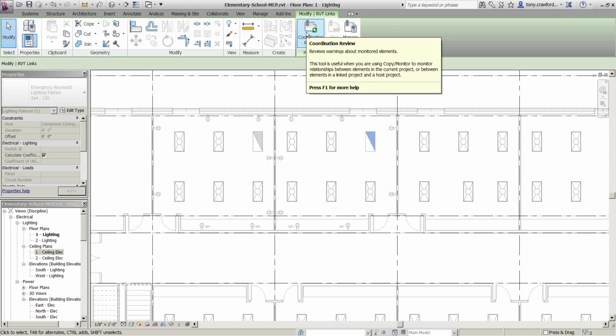And basically what that's telling Revit is keep monitoring these two, monitor mine versus the original, and if anything changes, make this the new normal. So now that they're really on top of each other, keep monitoring it, but use this as your reference point now instead of the original point where the insertions were the same.